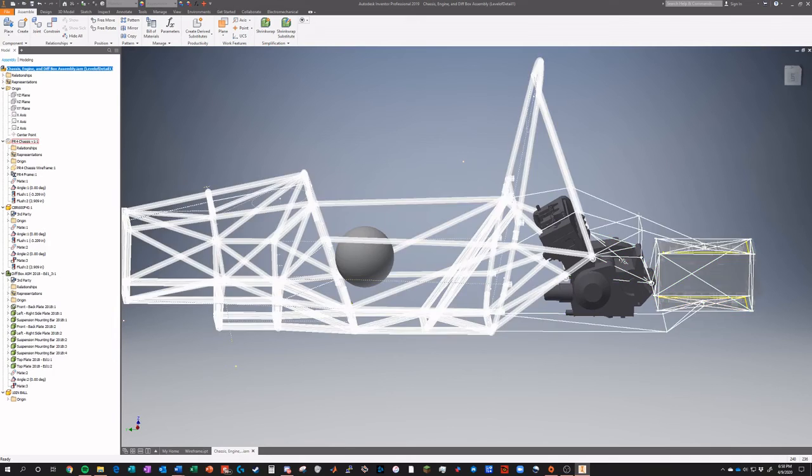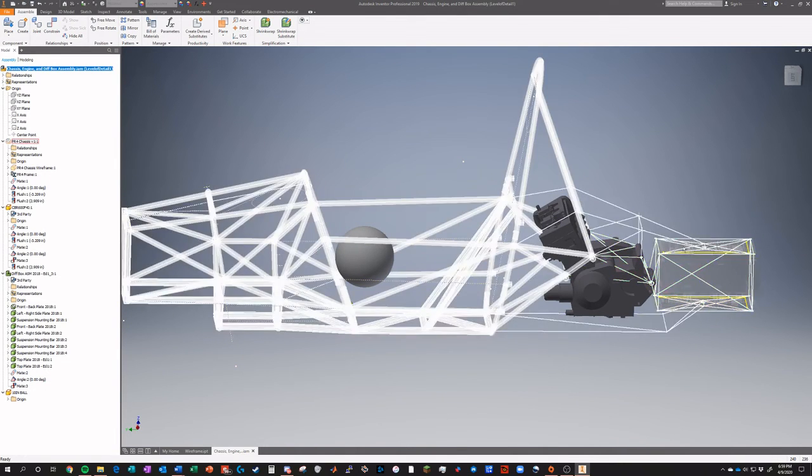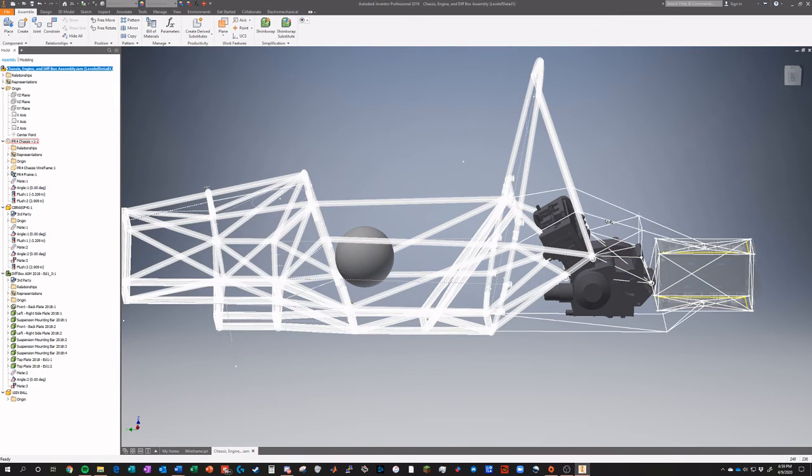And this one I wanted to talk about is, again, associated with the 3D sketch area. So what essentially happened here was the front of the frame geometry was set in stone, and we wanted to figure out what the rear geometry was going to be. Usually the way we'd done that traditionally was by placing the engine in the jig, and then assembling the diff box around it, and then kind of putting our frame tubes to it. I wanted to do that in CAD ahead of time so that we could get an idea of what strength properties that approach would give us.